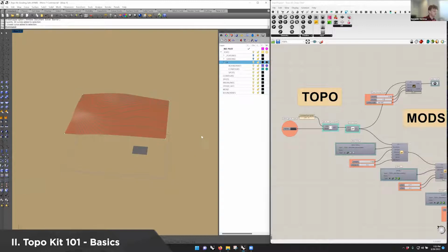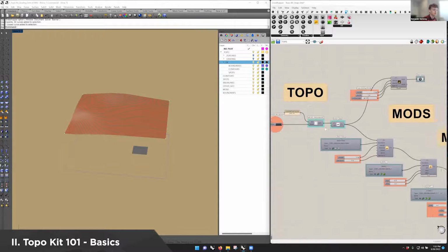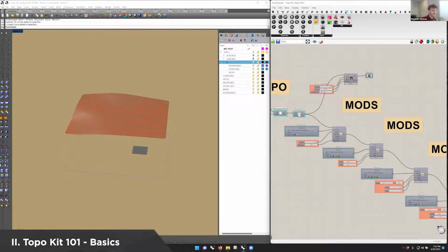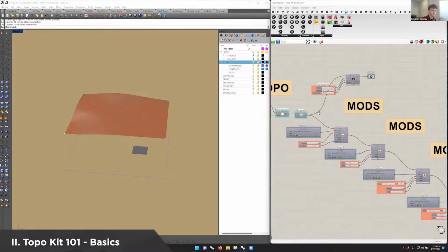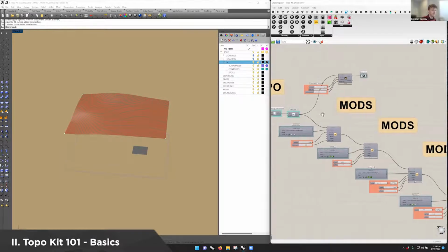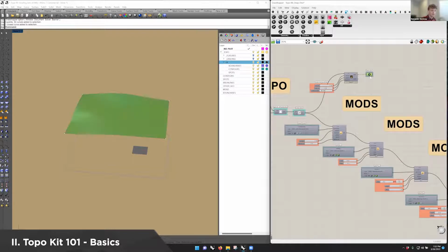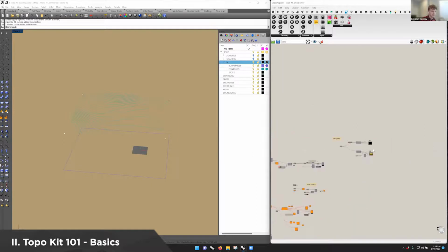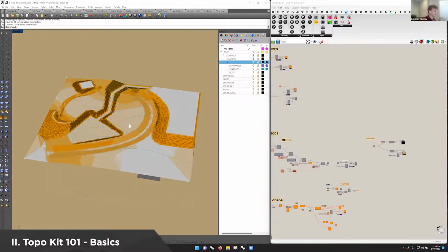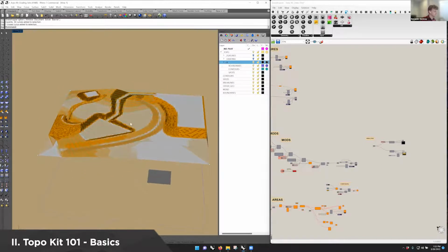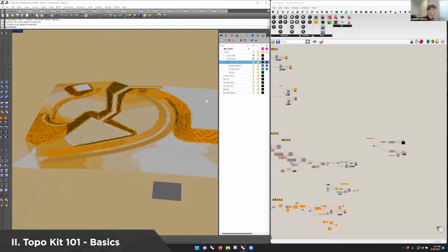But if I draw this point out here and I put it in the spots layer of existing, it will be excluded. So we basically work down the line, you create a topo, and Chris will show you a bit later how that incorporates with the features. We'll both talk about that. And you can draw the topo right away, and this is showing existing conditions. But we're going to talk a little bit more about how the mods work. So right now I'm just previewing a slope analysis. So all of this is showing a lighter color as flatter and a darker color as steeper slopes.